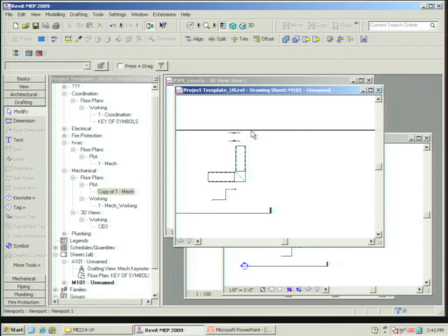Which is the same as the piping. One view has medium detail, one view has fine detail. So in the medium detail view, you just hide that riser by putting it under, let's say, a piping riser workset. You just hide that workset in medium detail and turn on that workset in fine detail, and just overlay those two views on each other. It's just going to work.